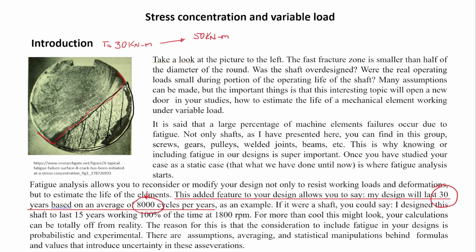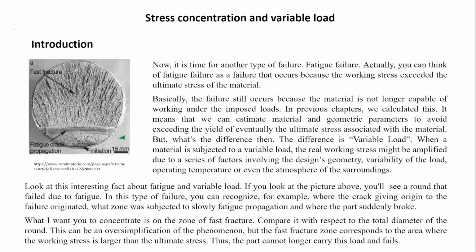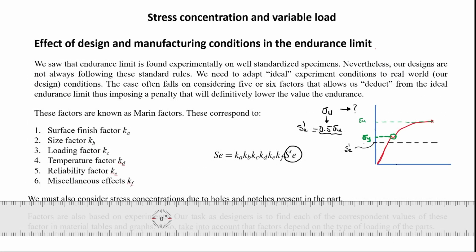So I don't say that this is half of the material, so it's half of the design, so it's half of the ultimate strength. No, by chance this picture is like that, and you can see this is very different. It's maybe 1/4 of the whole diameter. But what I want to say here is, imagine how much power we are taking from the material to resist things in our design, and besides that, we are applying safety factors to reduce even more the allowable values that we're using.